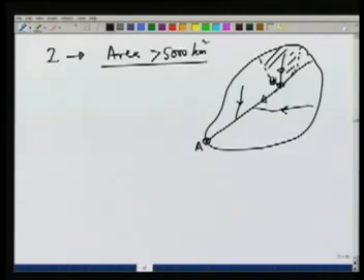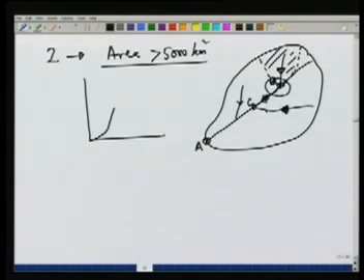But now this outflow at point B will go into the channel till it meets the outflow from another tributary, let's say at point C. So the direct runoff from the tributary will come at point B. It will travel through the stream and reach at point C, where it will again meet the runoff from this tributary. So if we find out at this point B the DRH, if we find out direct runoff hydrograph at point B, we will then have to add the base flow to it.